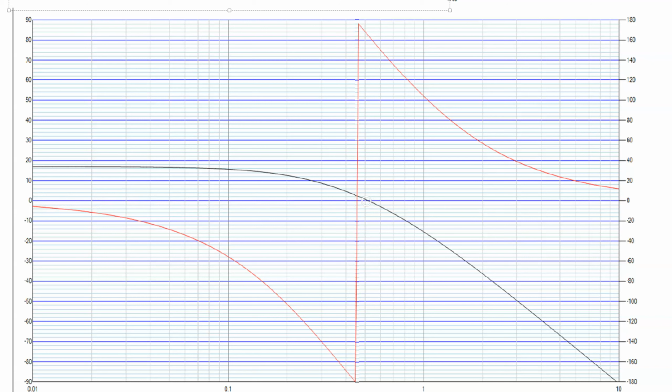Okay, 0 dB gives the omega d value. So this cross point, for example, would be the crossover frequency if the P controller gain is 1, which is 0 dB. So this is the process gain, and the Nyquist equations deal with the open loop Bode plot.